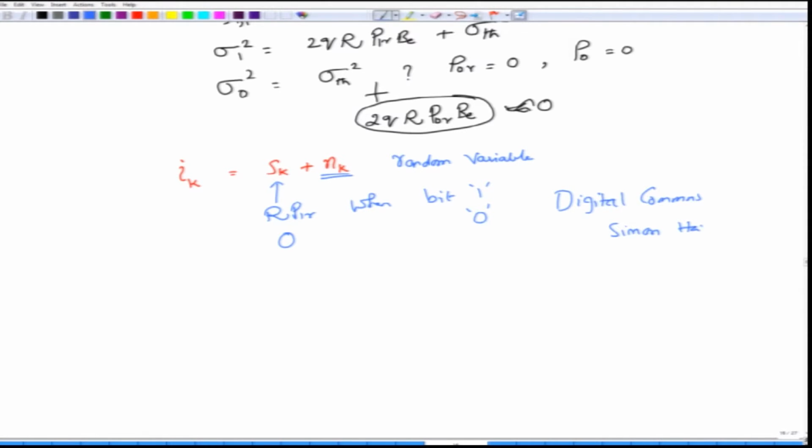Okay. So, if you look at this book, it gives you a nice idea of what probability is, what random variables are, and how these random variables are distributed. For us, noise is a random variable, and as I said, this noise variable Nk is usually modeled as a 0 mean, which is on an average the voltage of the noise is 0, but it has a certain variance sigma. Okay. This variance for when you transmit bit 1 will be sigma 1 square, when you transmit bit 0 this would be sigma 0 square. Usually sigma 1 square is larger than sigma 0 square.